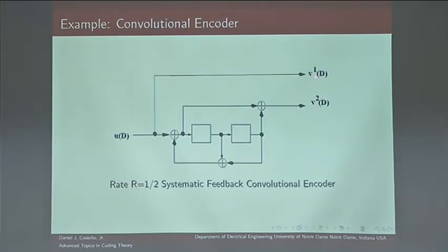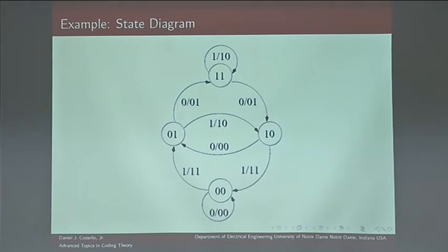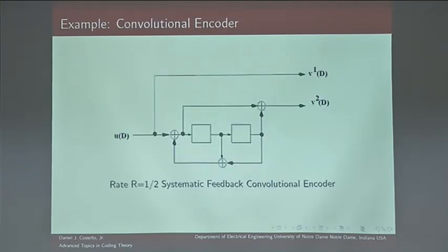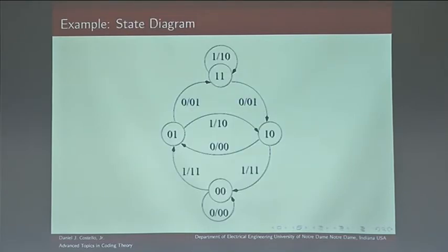Okay, well we're going to get a 1 out up here, but that's it, because, oh no, excuse me, that's not it. We have the 1 coming in here, 0's fed back, so we get a 1 coming out here. So we're going to get 1, 1. With the 1 input, we're going to get a 1, 1, and we have to see what the state is. So that 1 that gets fed up here, then the next time unit will move over here. And the 0 that was here will move down here. So the next state is going to be 1, 0.